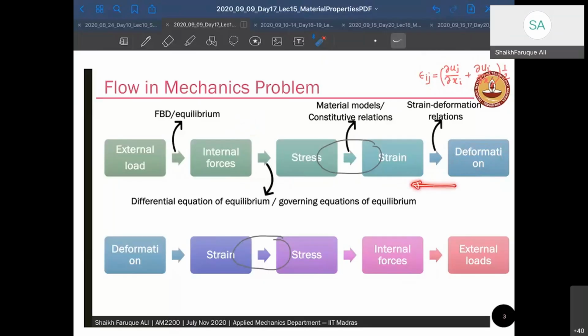So we were talking about finite elements. These are the two different ways of looking into materials in finite element also. So either you do deformation based or strain based formulation, or you do stress based formulation. Now, what relates both of them together is called constitutive relationship. Once you know the constitutive relationship, you can see the complete picture of how deformations and loads are related. How to get deformation from given loads on a structure, and how to get loads from given deformation on a structure.